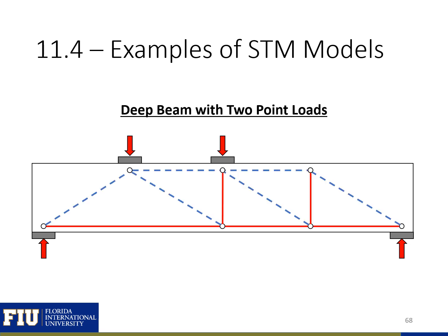And here we can connect those nodes and develop our strut-and-tie model with our tension ties being either vertical or horizontal here for easier constructability.